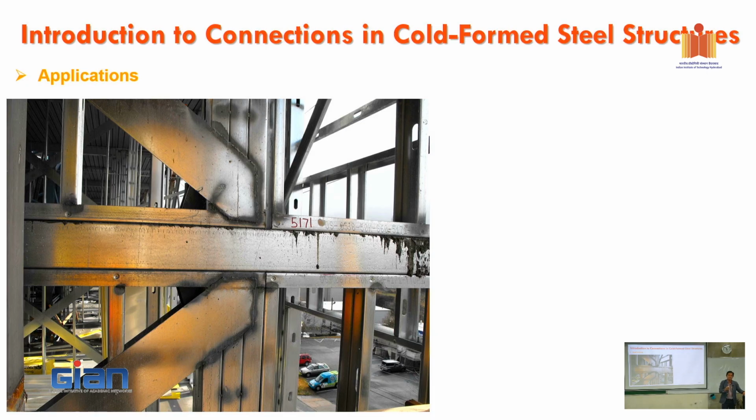Good? Do we test the screws in tension and shear? We test everything. I'll show you later, different failure modes, all right? We test in shear, in tilting, in bearing, in pull-out, in pull-over. There are different failure modes, so we have to make sure we don't miss any failure mode, as it might happen in practice.